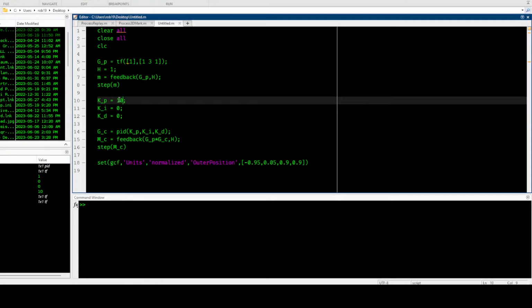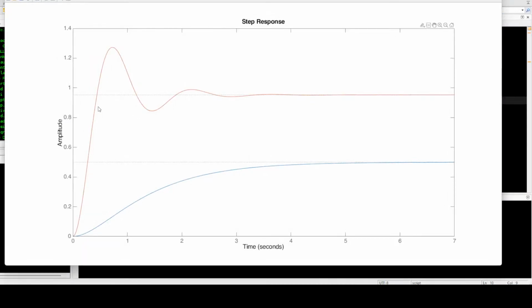And this problem becomes more and more problematic. You'll also notice that there's oscillations. So now we're going, oh, too far, oh, not too far, oh, less. It's like they're swinging back and forth like a drunk guy on the side of the road trying to touch his arms to his nose. This is the inherent problem with proportional control of a second order system.